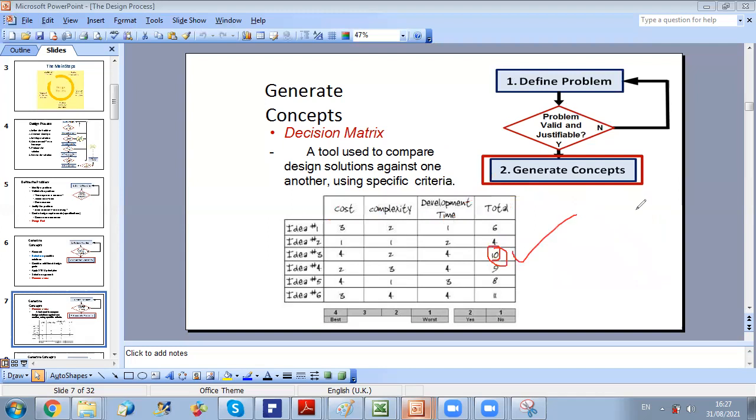Okay. So for example, if you want to advise to use something else, we can say, why not to change the system of ventilation? So instead of implementing something with it, maybe we can say maybe displacement ventilation is better. In general, displacement ventilation is better for air quality in some cases because it will provide fresh air from low level, and then the exit is at high level, so it can help into transport of contaminations.